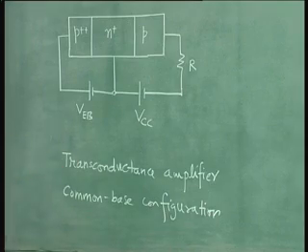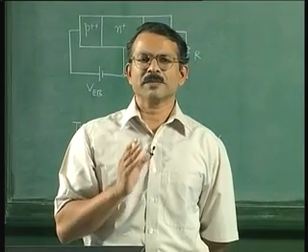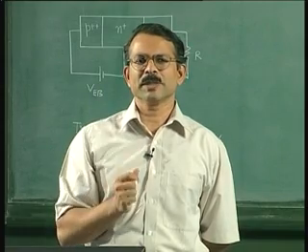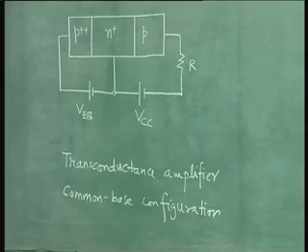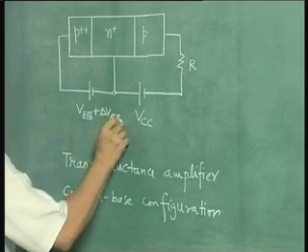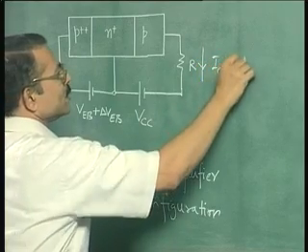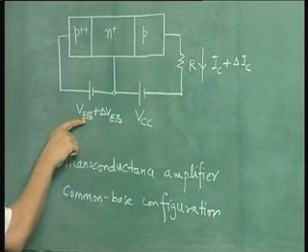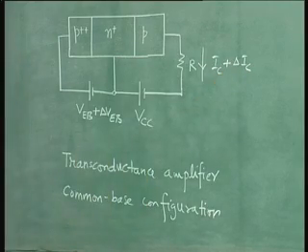The capability of the bipolar junction transistor to amplify small signals is more easily understood when you derive it from first principles, using the common base configuration and regarding it as a transconductance amplifier. If you increment the emitter base voltage, the result is an increment in the collector current. So you have IC plus delta IC, meaning the current IC corresponds to the voltage condition VEB. When you increment VEB by delta VEB, IC increments by delta IC.